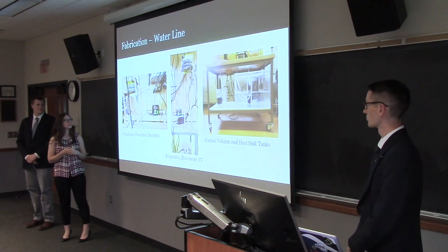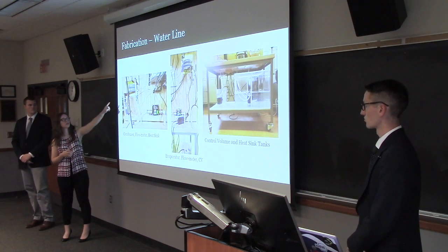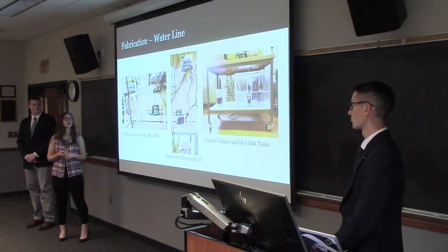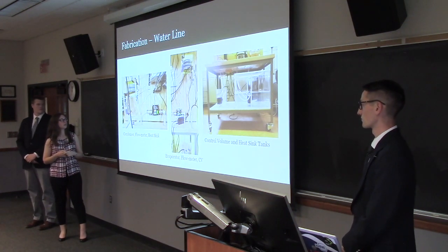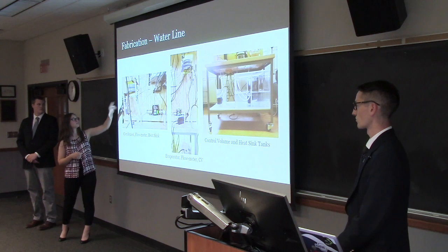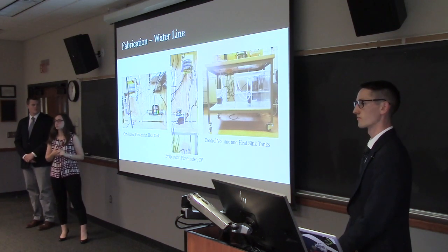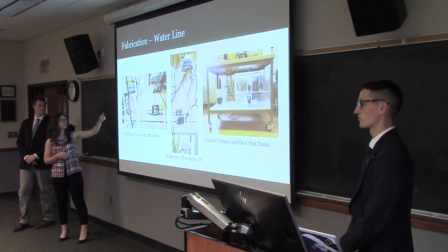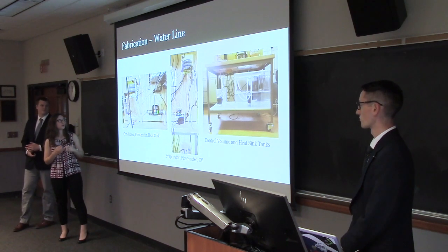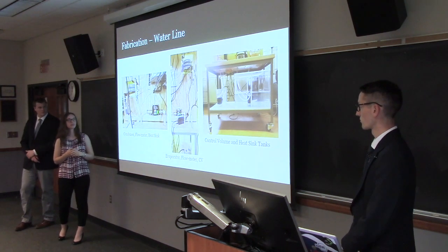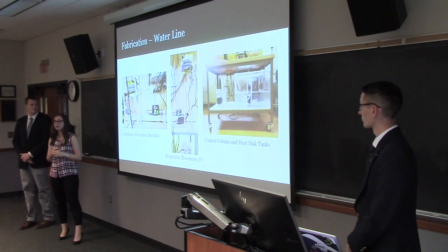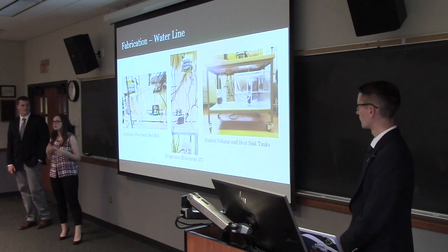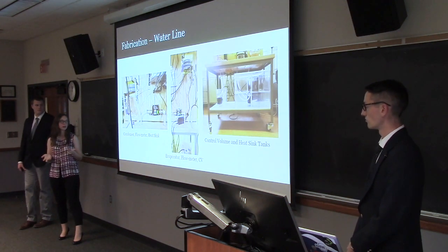The order of installation here started with the mounting of the 2 heat exchangers, the condenser and the evaporator, so that the solder team could get going with the copper pipe. And then they also soldered on these solder-to-NPT elbows as well. The other type of connection we used on the water line is a barb fitting with a worm gear to an NPT with Teflon tape. The tubing was hooked up so that the heat exchangers, both of them, would be counterflow to maximize the heat transfer between the Freon and the water.